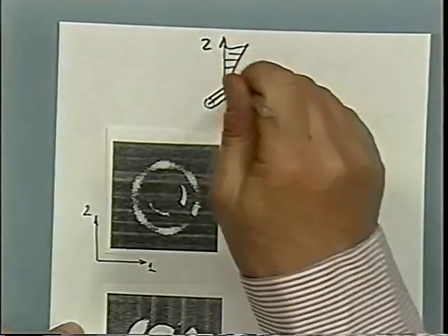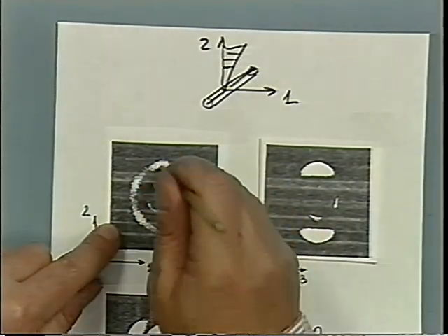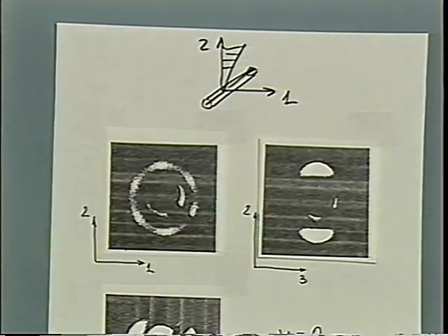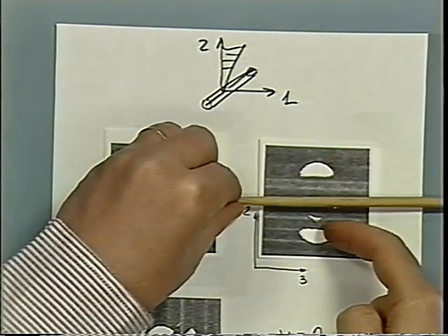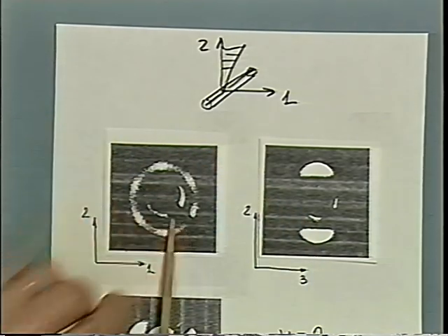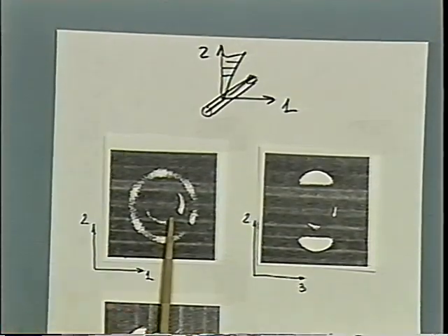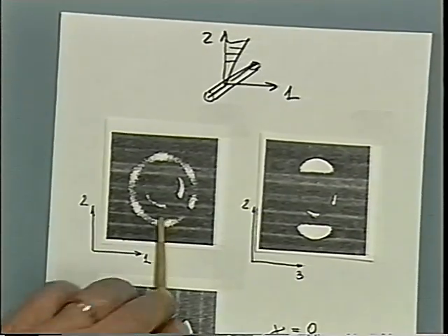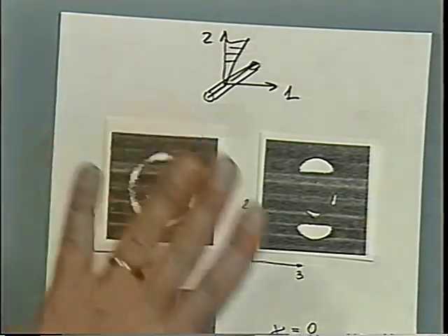We're first looking at the 1-2 plane here, and the cylinders are aligned, and you can see that the reflection is in top and bottom, so our hexagon planes are like this. And the cylinders and the sample looked sideways are showing these reflections, and the cylinders going sideways are showing these reflections. And you can see that the reflections when looking at the sample from the top are a little more arced, so the order is not as severe as sideways where we have smaller arcs and the order is higher. That's the initial structure we are going to deform in a shearing experiment.